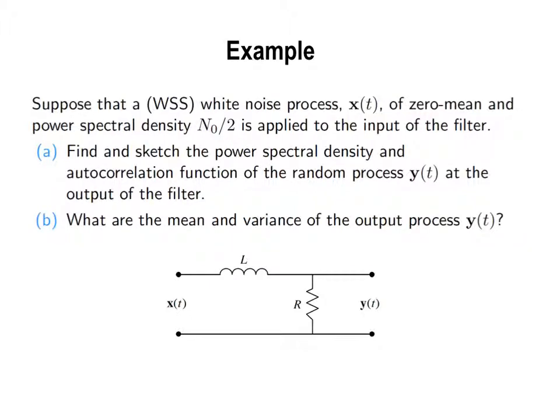For example, here we have background radiations. It's not thermal noise, so it's noise. But the definition says that noise means thermal noise. But background radiation, from the perspective of a communication system, is extra, like what we don't need? No, it's not only that we don't need it. They are very, very, very low as compared to the thermal noise in the receiver.